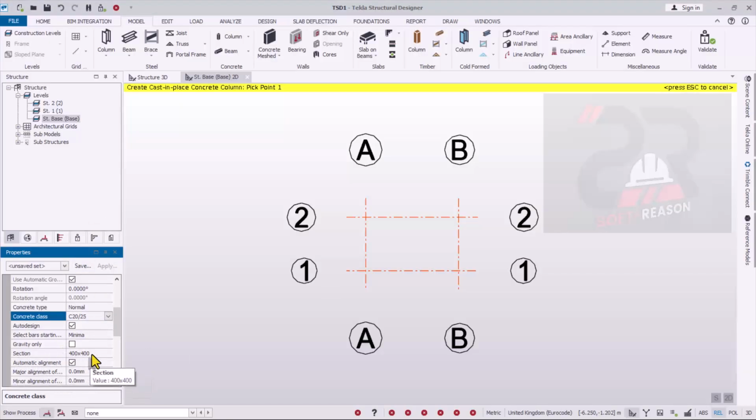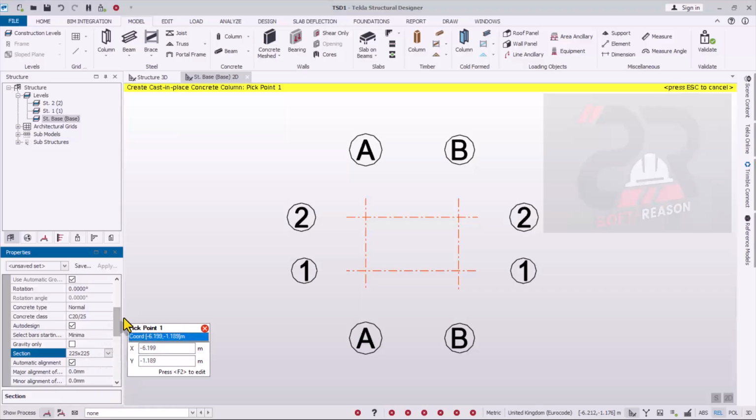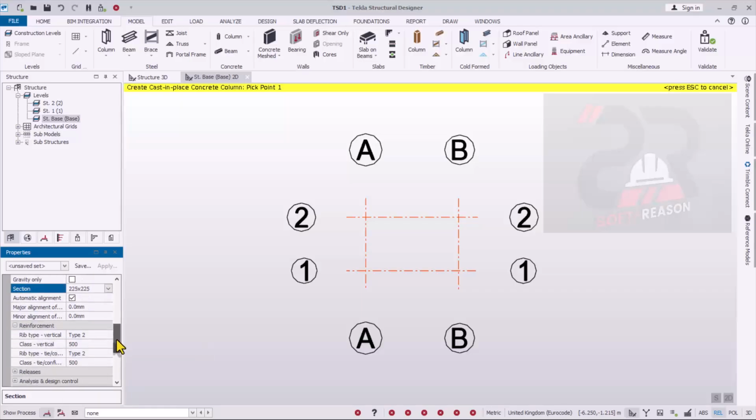For the column sections right there, select in use provisions, and then we use the minimum column sections. Minimum column section is 225 by 225. This is the minimum column section. All right, so we try this section and see if it will be able to carry a water capacity of 10,000 liters. All right, so click on the OK option. We scroll down right here, and every other thing, I think we leave as default for now. Okay, the nominal cover is 35.